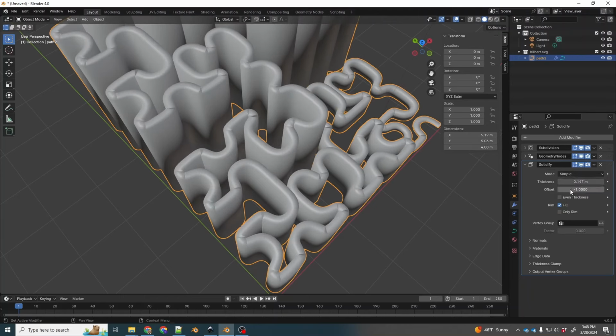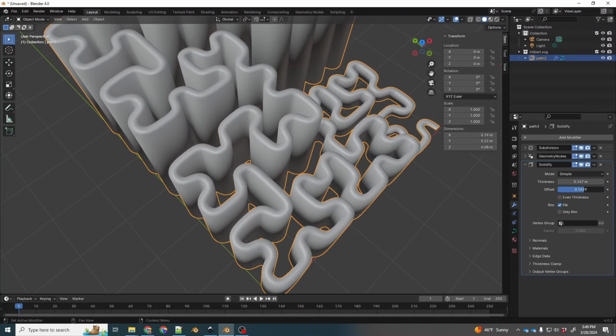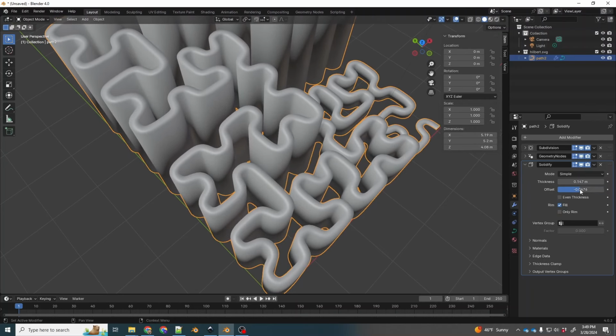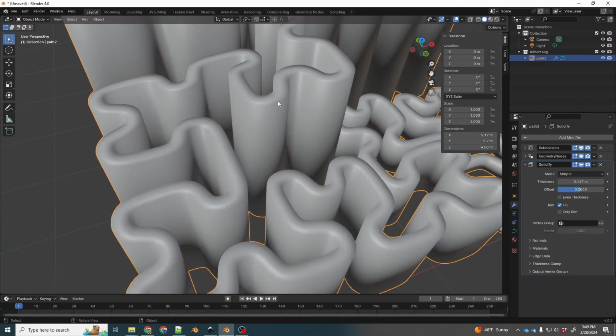Okay. The next parameter, offset, determines at which side of the curve you are increasing or decreasing. So this is on the left side, you can say, and this is on the right side. We don't want to choose left or right. We want to be right in the middle of the track. So we're going to set this to 0. Now again, it's a thick wall now, but the ball cannot roll on the track.